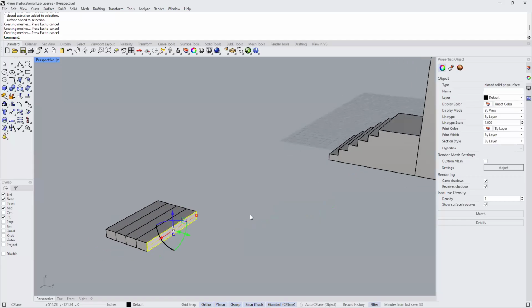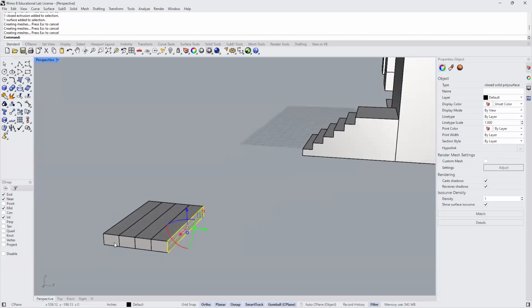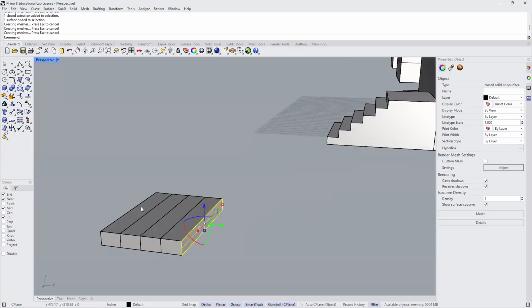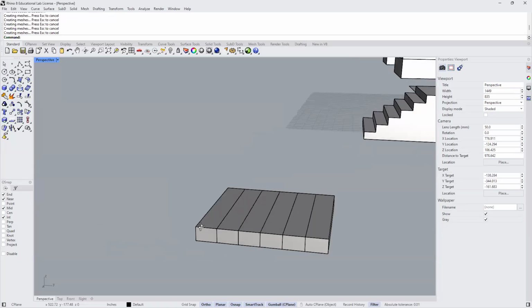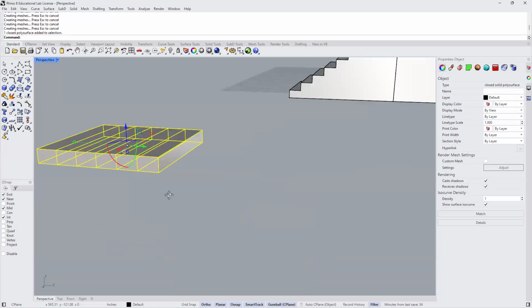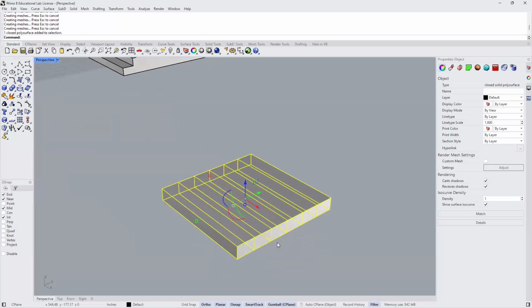Let me pan over. So as I study this, this will be the first 8 inches. So that's 8 plus 8 plus 8. I'm at 24. So I need to do this 2 more times. Click, 12 it is, enter, click, enter. And then let me just tap the escape key. So let's see, 1, 2, 3, and 1, 2, 3. Great.